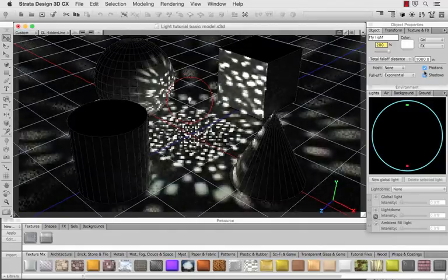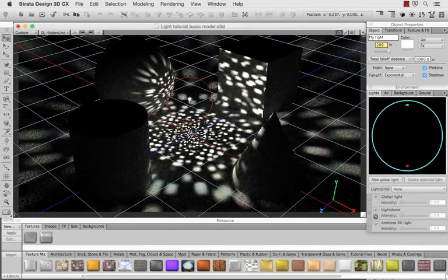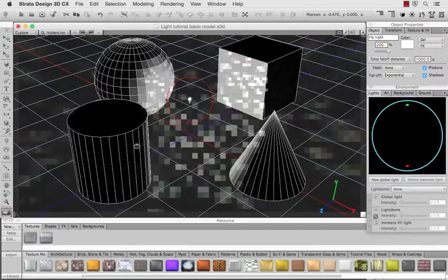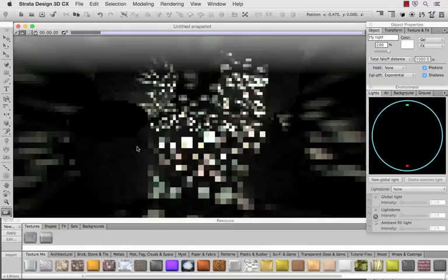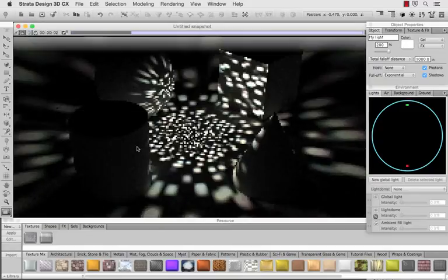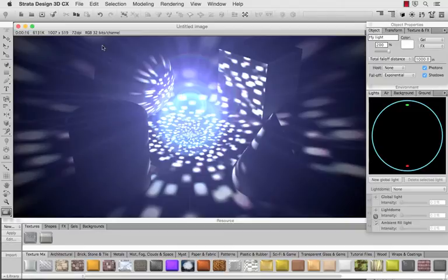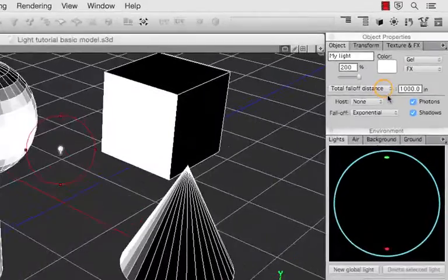Live Ray renders the disco ball gel because gels are what are referred to as in-render effects. The lens flare is a post-render effect. So to see the lens flare, we have to use the rendering tool to see the effect. I'll remove these effects so we can more closely see the effect of the remaining settings.